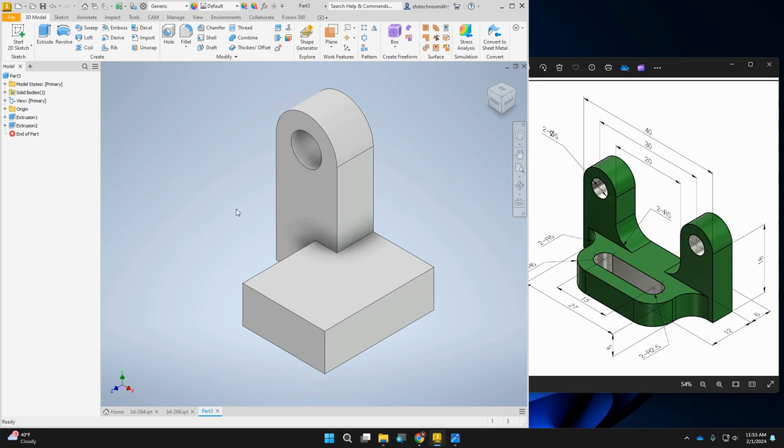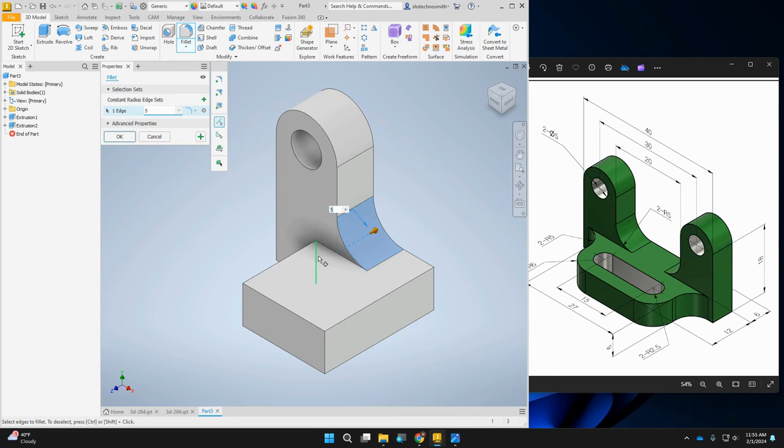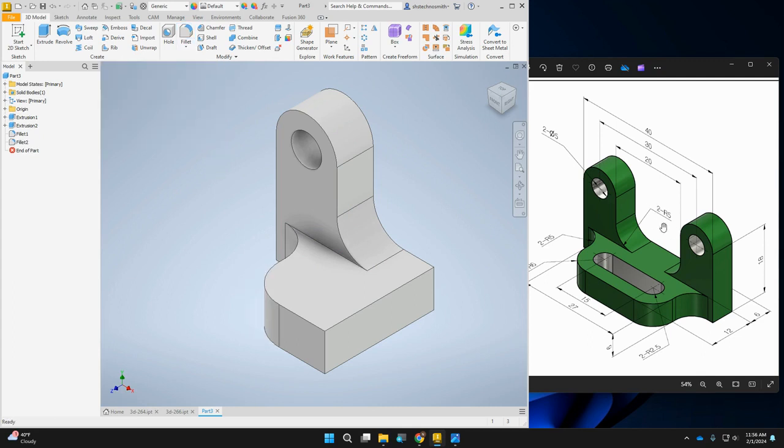All right, so now I'm going to do the slot afterwards because as we saw in how we do the slot, it'll do the whole thing. I don't want to do half of it. So now I'm going to start adding the roundovers. Okay, so my fillets, I've got a couple that are at 5 millimeters. So I've got one there and one there. Notice I don't have to spin it around. I kind of know where it is and it'll find it. And we'll hit OK. And then I have a fillet here of 6. So we've created half of this.